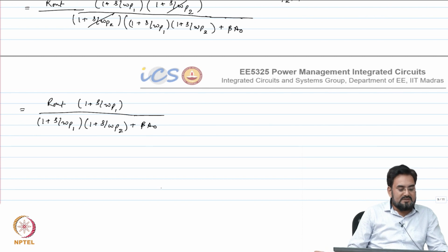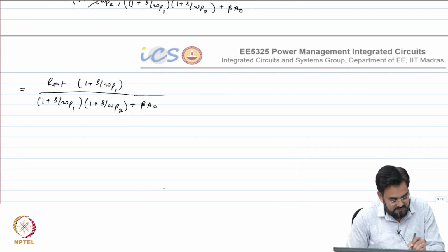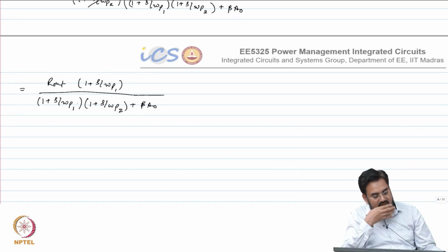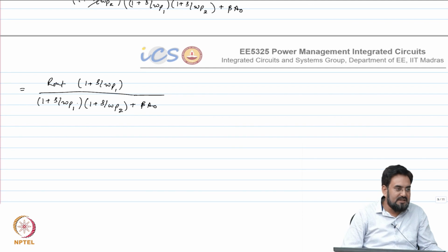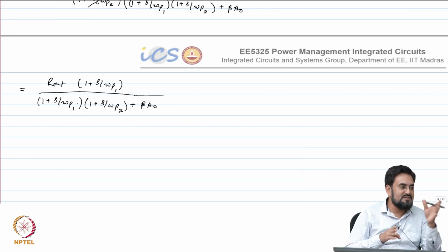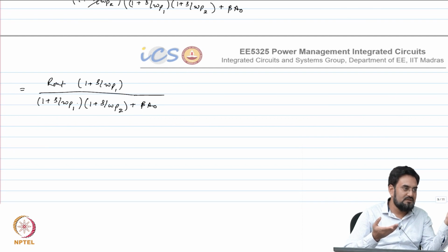So we have 2 poles and 1 zero. Now we have to simplify this and find where the poles are. So the denominator, if you break the loop, will become a quadratic equation and it will complicate things. So how can I simplify this? So consider a compensated loop. Can I say that before UGB you will have only one pole? The second pole will be outside UGB.